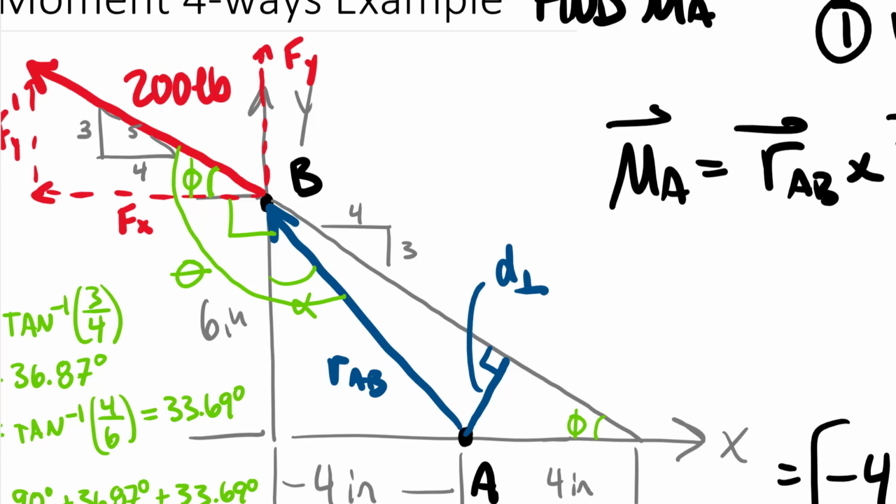Okay, I know that angle is also phi because fundamentally I have that this line, which is parallel to the x-axis, is bisected by this big line of action. And we know that any two angles along basically a line bisecting parallel lines are going to be exactly the same. So you can go ahead and put that if you wanted to as the 36.87.